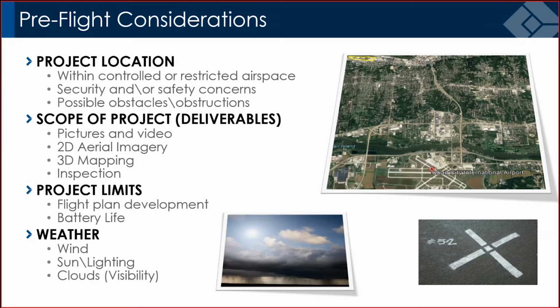Is it within controlled airspace? We need to account for security. We need to really understand what the limits are because of our battery life, right? Data storage: the bigger the site, the more data that we're going to collect. On our drones, there's a 64 gigabyte data card on it. So depending on how big the site is, we need to make sure we have enough data storage to handle that.